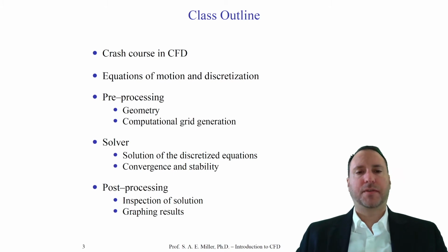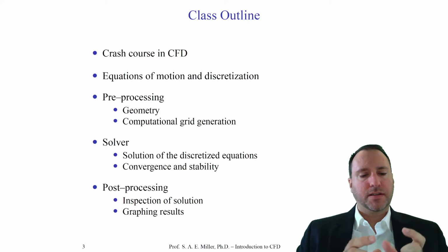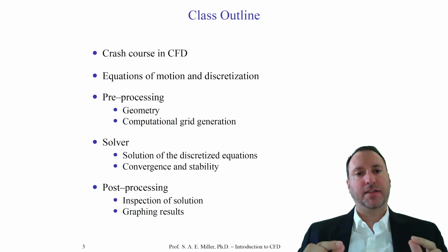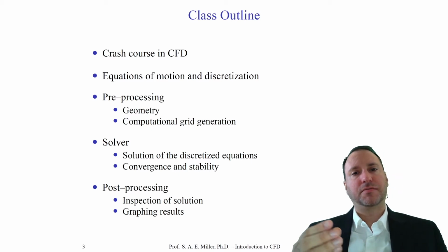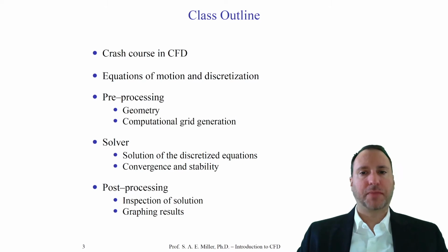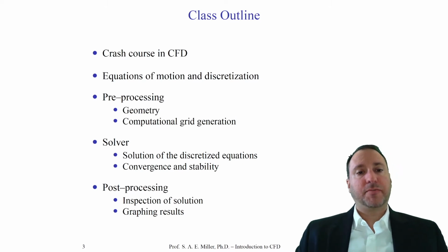And of course, some people doing more theoretical work might be looking at higher dimension fluid dynamics. Computational grid generation is where most people spend their time in computational fluid dynamics, and this is no different. So this is where we're creating the grid points and connectivity, which is used to discretize the equations of motion into the computational domain.